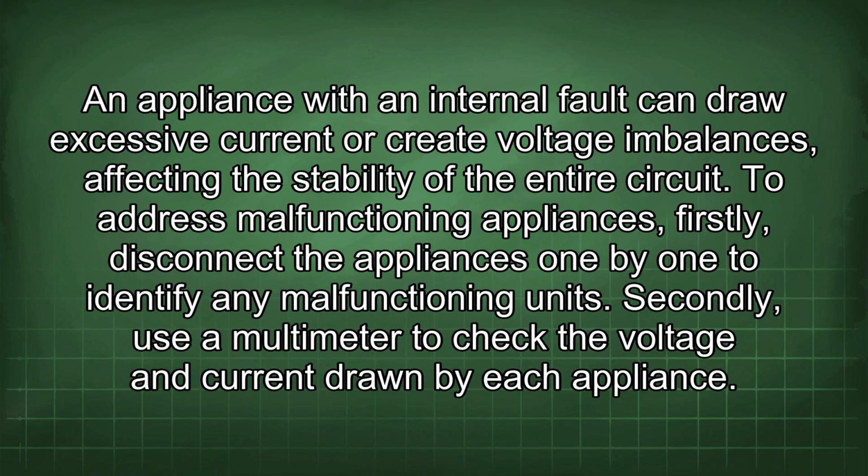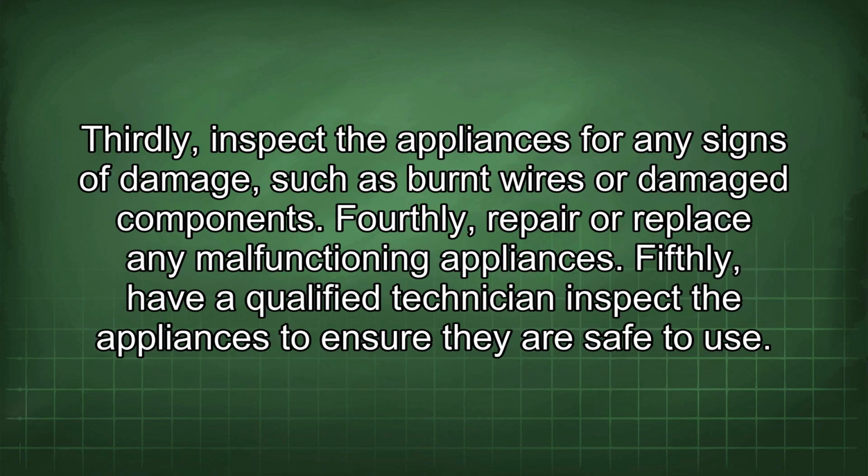Secondly, use a multimeter to check the voltage and current drawn by each appliance. Thirdly, inspect the appliances for any signs of damage, such as burnt wires or damaged components. Fourthly, repair or replace any malfunctioning appliances. Fifthly, have a qualified technician inspect the appliances to ensure they are safe to use.